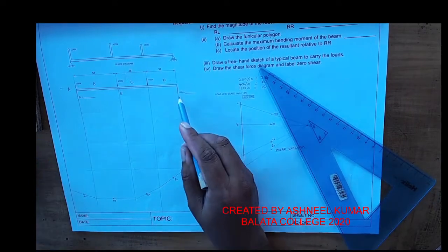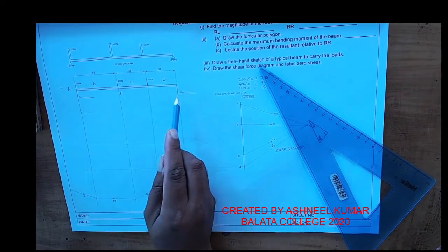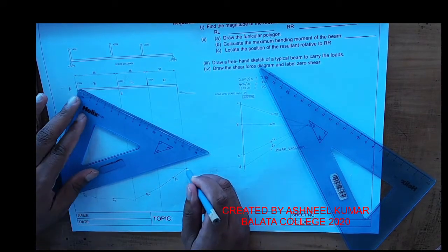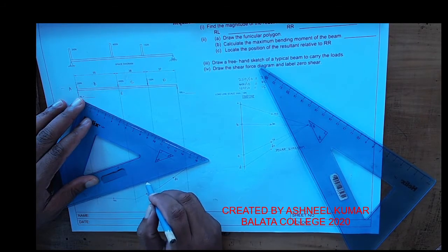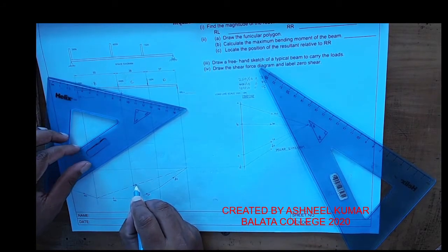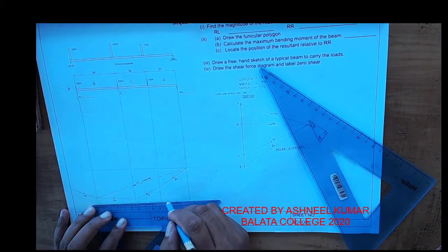Now your E is from RR to RL. So I'm going to join from this point till this point. I'm not going to join it here because your E is from this line to that line only. You can label this as your funicular polygon.